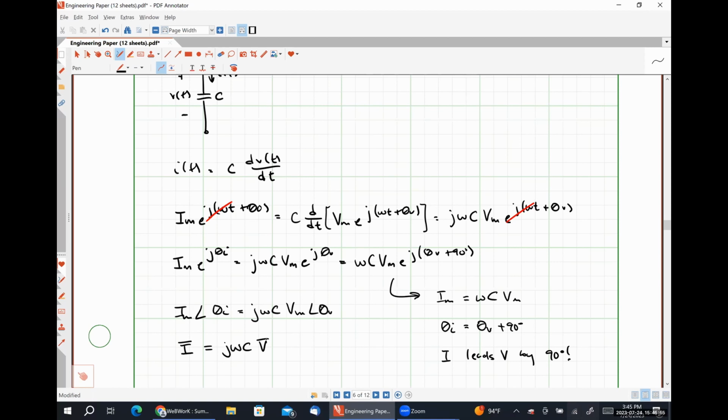So my goal here is to take these time domain steady state sinusoidal circuits and give us the tools to convert them into the frequency domain so that we can effectively just do simple DC circuit analysis to get our AC results. So for things to be a bit confusing right now is perfectly reasonable, because I'm not quite finished yet. But once we talk about the concept of impedance, we'll be able to tie everything together and then apply simple techniques, Ohm's law, KCL, KVL, voltage division, current division, things that we've been doing, to these complicated AC systems, and really just do all of the exact same analysis that we've been doing previously. Now we're just using complex numbers.